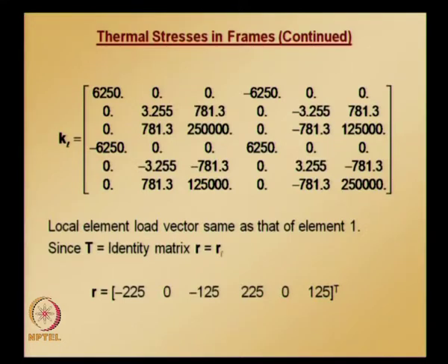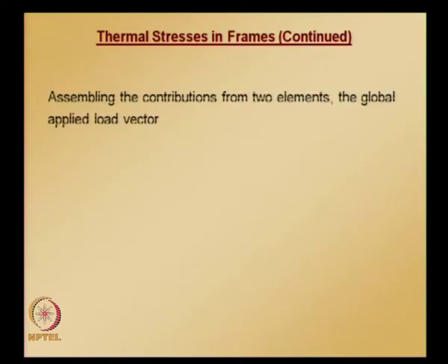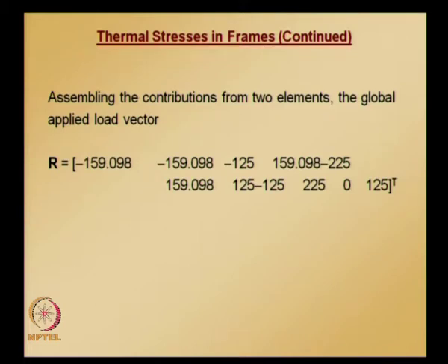Because of the boundary condition, all the degrees of freedom at node 1 and node 3 are 0, so there is no need to assemble the corresponding rows and columns. Since the specified values are 0, the corresponding columns will not contribute anything either. Thus, in the following global equations, only the terms associated with node 2 are written,